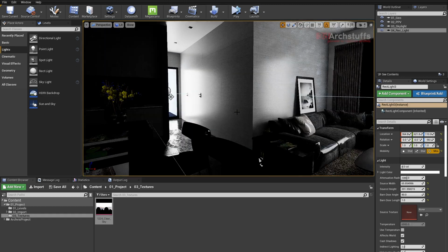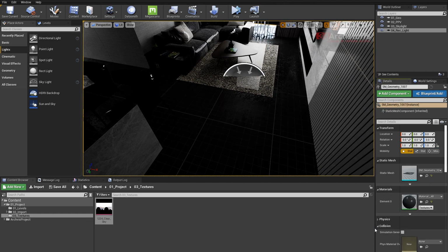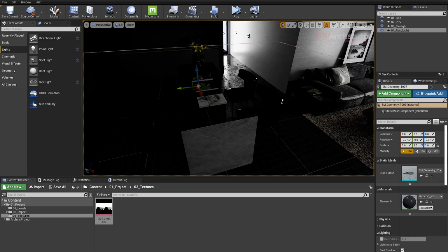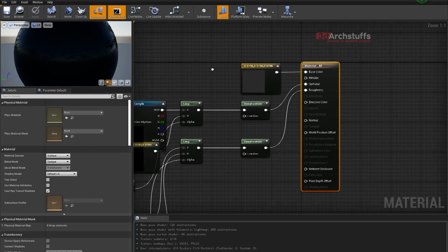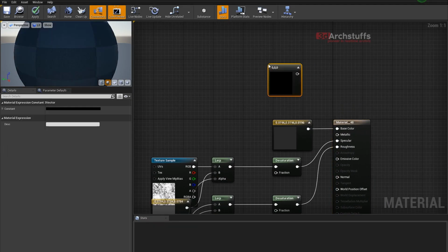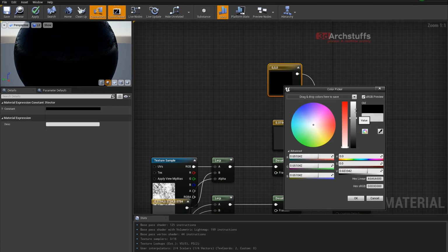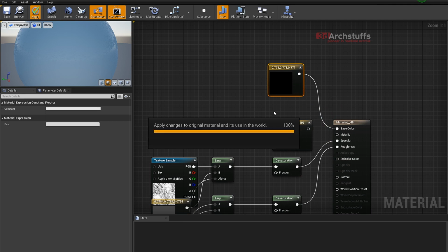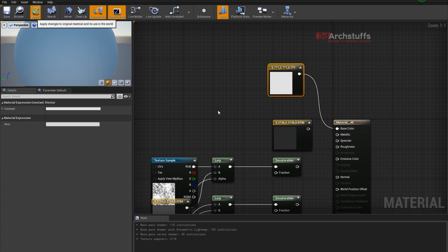And now we'll change this floor's material to white as of now, because somehow Unreal Datasmith has not done a good job importing and converting the material of this floor. So let's make it white. I will press 3 and then click on the viewport, and then I will apply a base color and make it this much white, and then apply it. And maybe I will switch off roughness and specularity as of now.